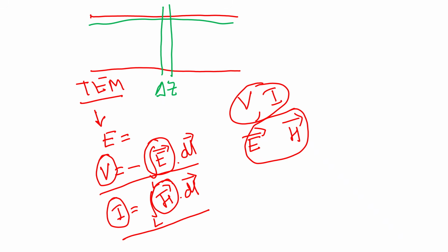Let us assume that this complete length is z, and we are just focusing on this small length del z, because in that small length we can assume voltage and current to remain constant over a certain period of time, and hence we can apply the theories or formulas of circuit theory. So my equivalent circuit for the small length portion del z will be something like this.